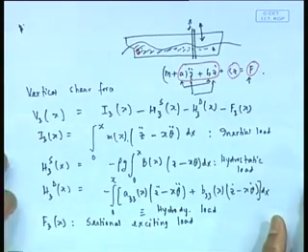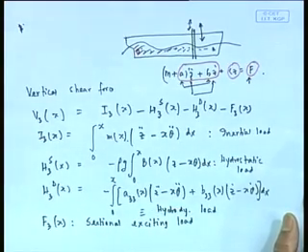The final part I said is that when you do Seakeeping, there are many outputs coming up. One also wants to know, especially the structural designer, what is my wave induced bending moment considering Seakeeping, considering the motions. And this is not what you have done earlier, if you remember, because in the earlier wave bending moment calculation, in fact, there is no dynamics involved at all. Simply one assumes that the wave profile is stationary and we need to get the trochoidal profile.